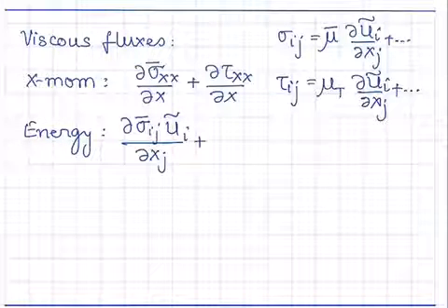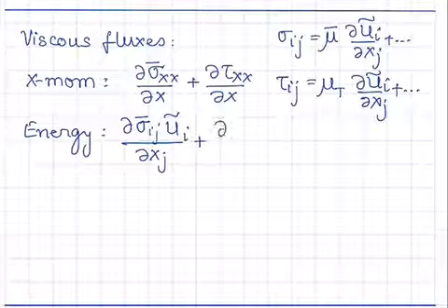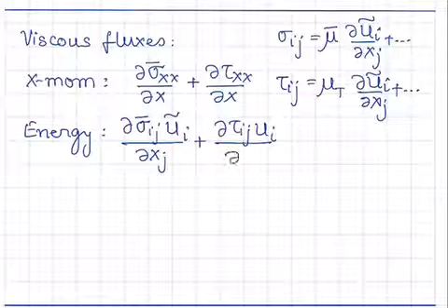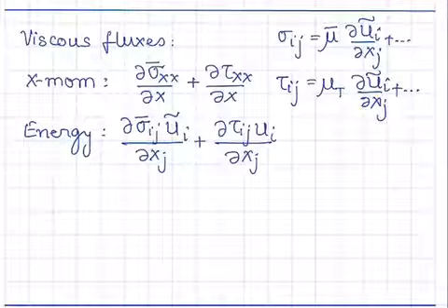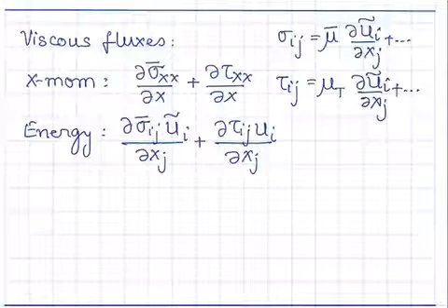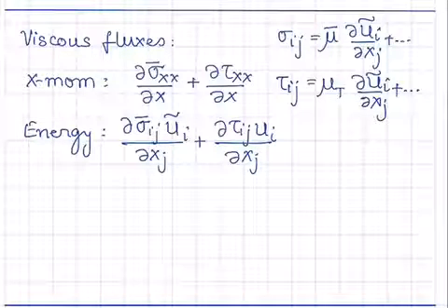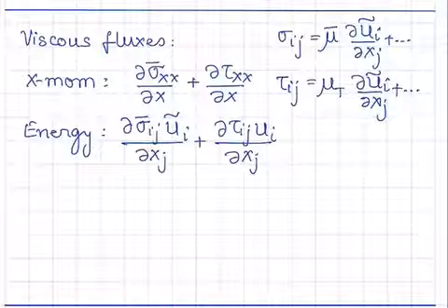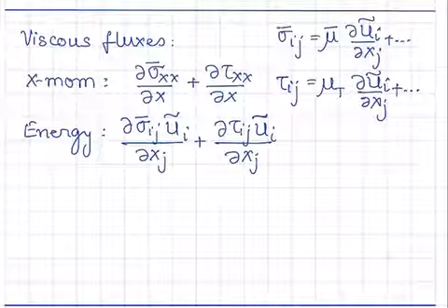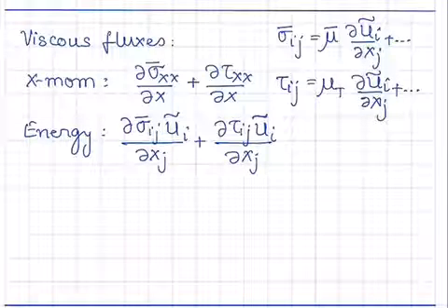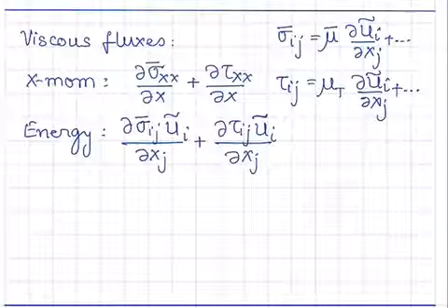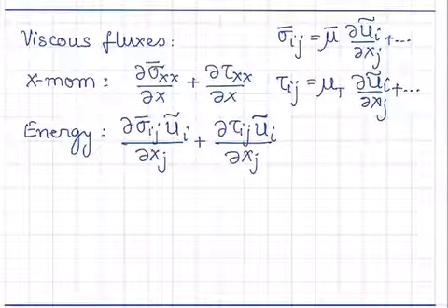We have another term which is the work done by the Reynolds stresses, tau ij ui, dxj. Tau ij is again a turbulent mean quantity. We generally do not put a bar on top of it. U has a tilde on top of that. Sigma has a bar. So these are a summation over 9 terms, both i and j varying from 1 to 3 in a general 3-dimensional flow.